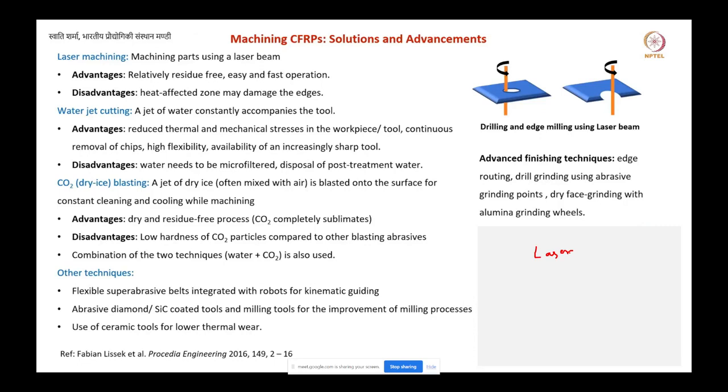And if you will do a water jet, a jet of water constantly accompanies the tool. So you will continuously have a high force of water, and that will accompany the tool. So the advantage is they reduce the thermal load. Okay, so your material won't get heated so much. So there is a reduction in the thermal and the mechanical stress in your tool, and there will be continuous removal of your chips, and it will give you a high flexibility as well as increase the sharpness